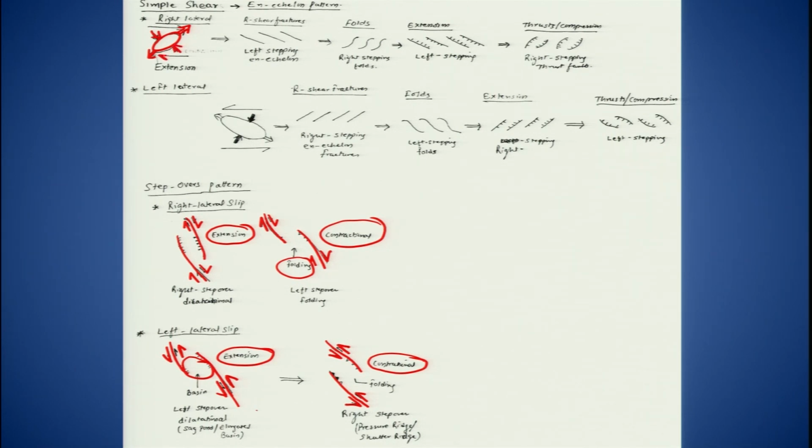The movement we see is the right lateral movement, and the shear fractures or Riedel fractures we will be able to see in terms of what we were talking about, the high angle and low angle with respect to the principal deformation zone. The synthetic one is your low angle, and the antithetic fractures will be at high angle.